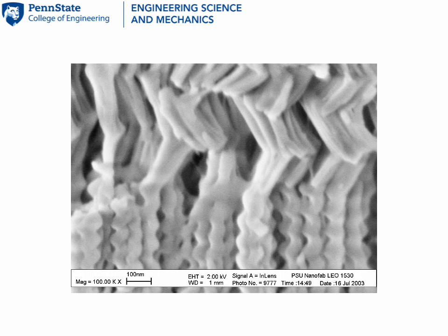The change of shape can occur within 20 to 30 nanometers of growth, which is optically abrupt. This is because sculptured thin films comprise 1 to 3 nanometer clusters as building blocks. The intercolumnar as well as the intercluster porosities can be controlled by varying the deposition conditions.